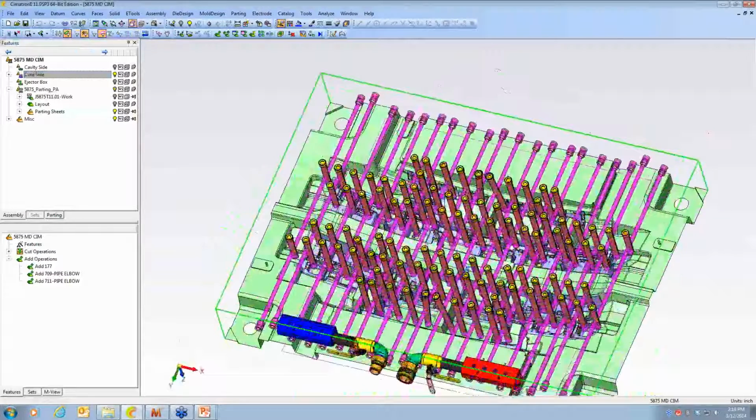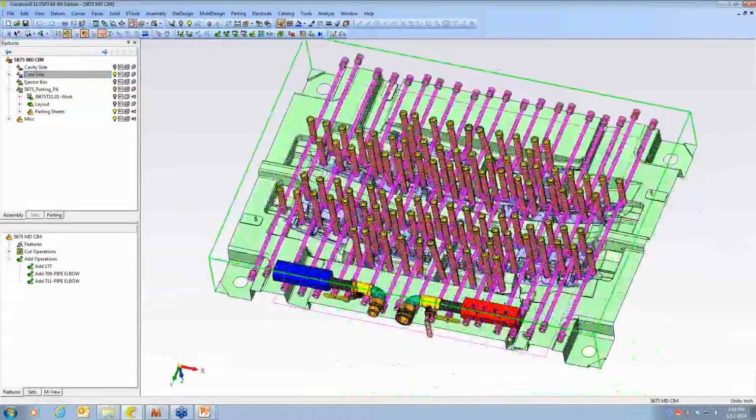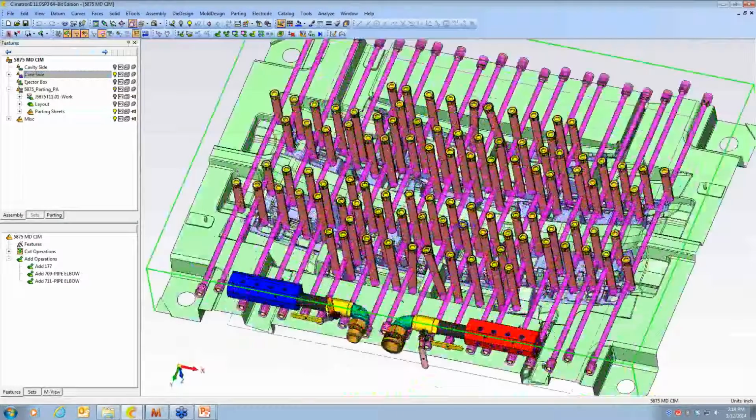The general school of thought is that even a rise toward the part of 1.5 inches is worth placing a baffle to gain. And many shops that work on jobs like this have 5-axis gun drill capability now. So baffles or water lines at angles are usually not a problem, and they're used to get cooling lines in where they're really needed the most.